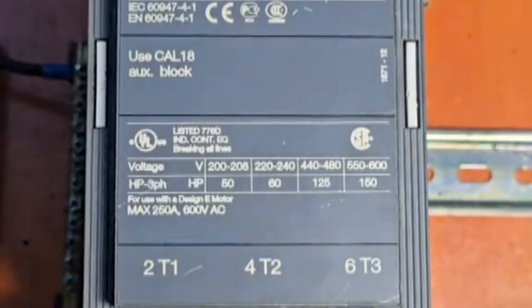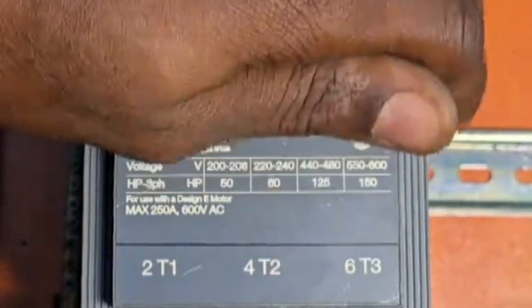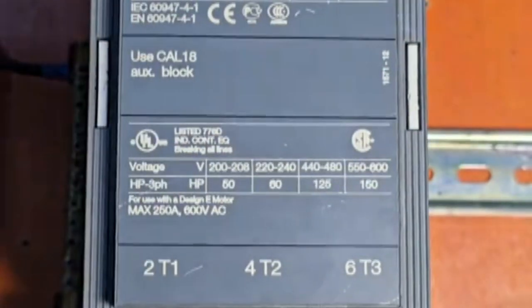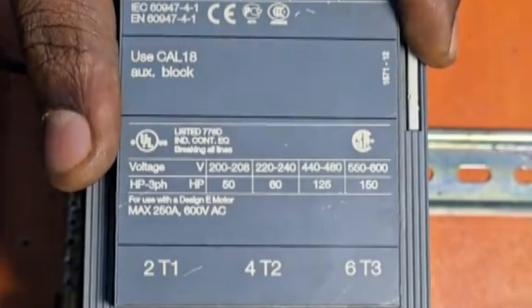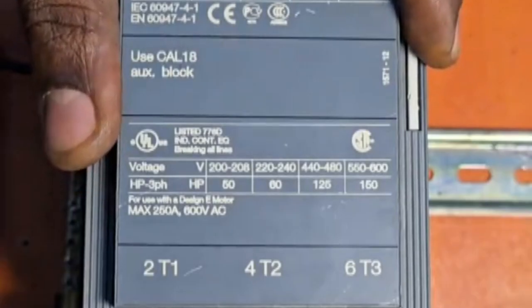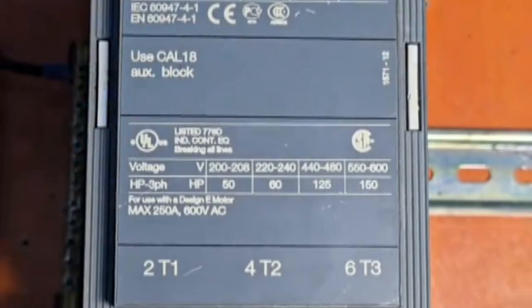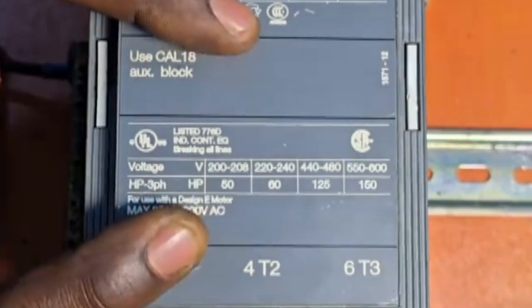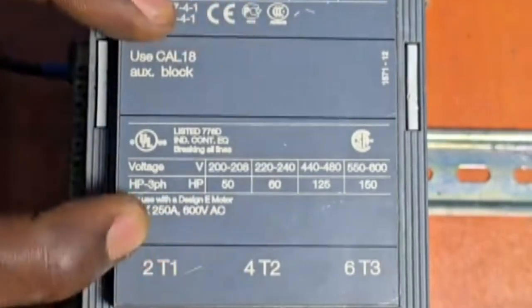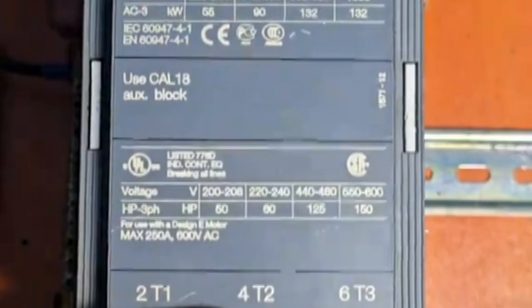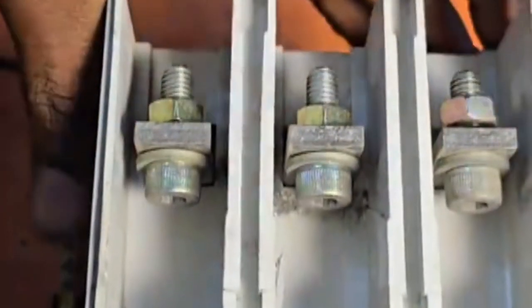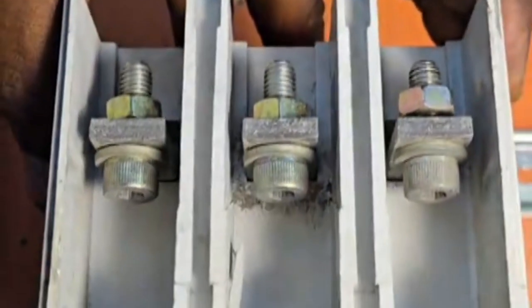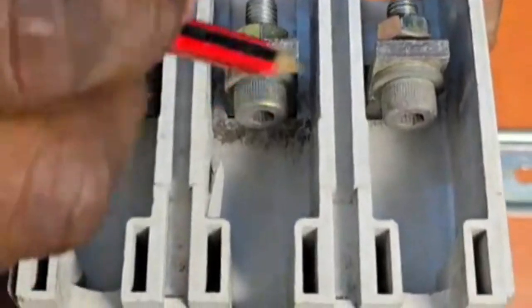In today's class, I want to take you through this beautiful piece of device, which we call a contactor. A contactor is just a switch, and it is a switch that is operated making use of electricity. So it is not just a mechanical switch, it is an electromechanical switch. What that means is that before this switch will operate, you must connect electricity to it. All right? So this is a three-phase switch or a three-pole switch, as you can see, 1, 2, and 3.